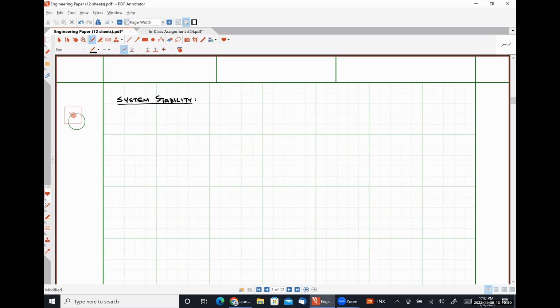Okay. So for a single pole system, the maximum phase shift that can occur is 90 degrees. And so these systems are effectively unconditionally stable. In a multi-pole system, the maximum phase shift will be greater than or equal to 180 degrees, and the system risks becoming unstable. This risk can be summarized by a plot in the S-plane diagram.